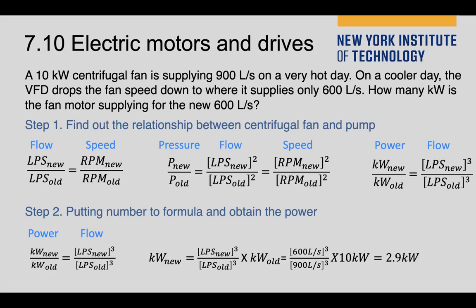So if the motor is constant speed, no matter what the situation is, the speed is constant, you will consume some more energy in summertime, because you need to make use of your valve to control the flow rate. But if the motor can adjust the speed and adjust the flow rate, the pump flow rate.